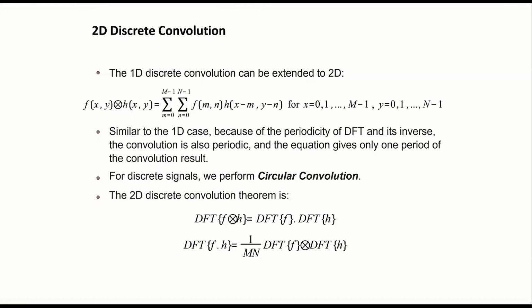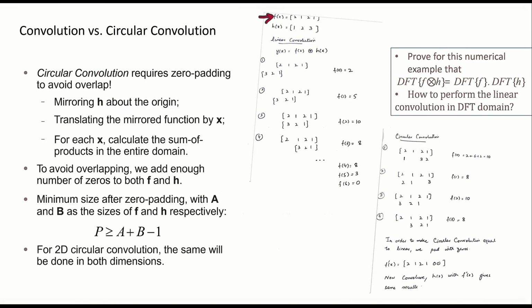What a circular convolution means is that, for example, I have an example. The problem is that all the examples of convolution and filtering that we were doing were with the simple convolution, which we call linear convolution, not the circular one. So we have to find a way to convert the circular to linear without disturbing its properties as well. So if I have a signal, say 1, 2, 3, and a filter, if I just take a simple convolution, how do I do this? It's simple. First I have to reverse it, so 3, 2, 1, and then I multiply terms like that and assume everything else is 0. This is what we were doing before.